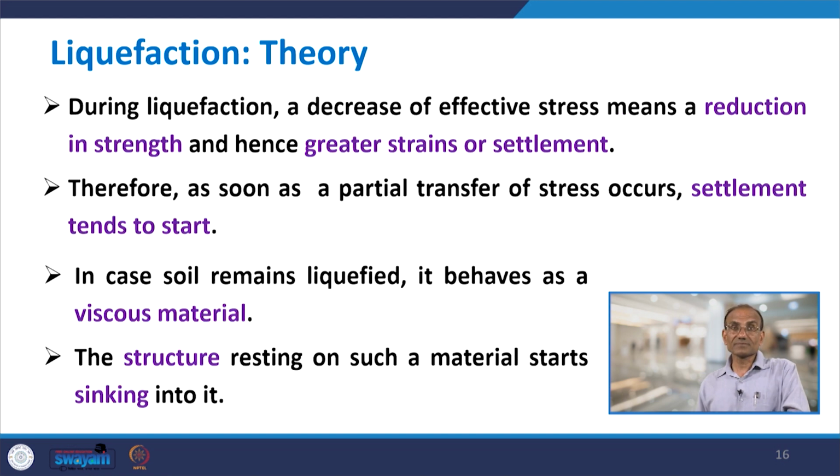During liquefaction, a decrease of effective stress means a reduction in strength, hence greater settlement will take place. What happens during liquefaction? We expect two issues related to foundations. One is that the bearing capacity of the foundation may decrease. At the same time there may be excessive or large settlement due to the liquefaction phenomenon. Therefore, as soon as partial transfer of stress occurs, settlement tends to start.